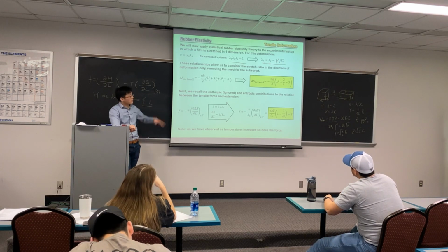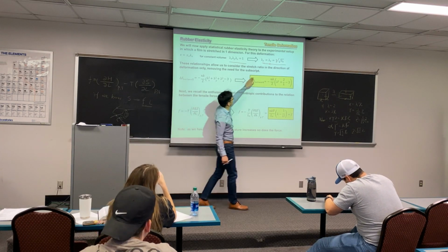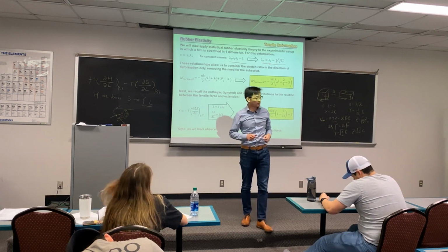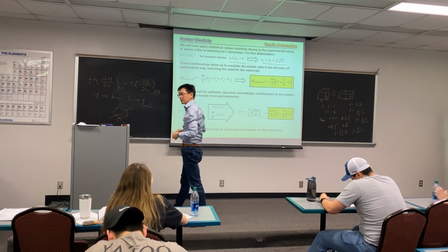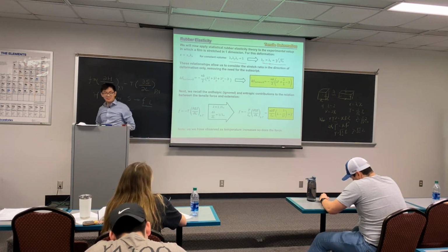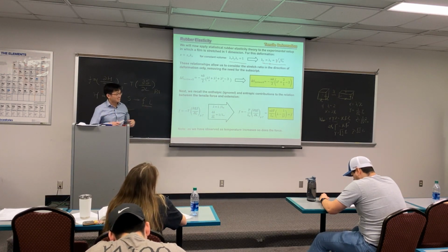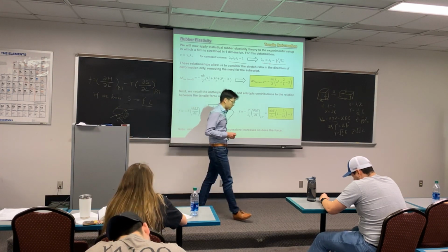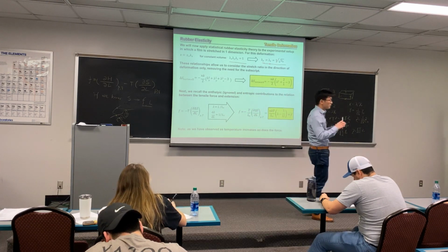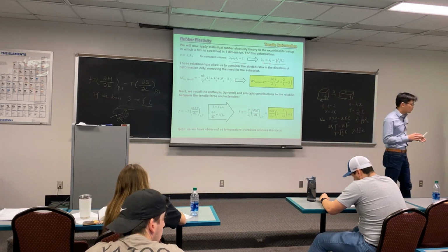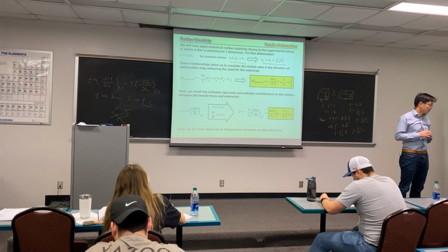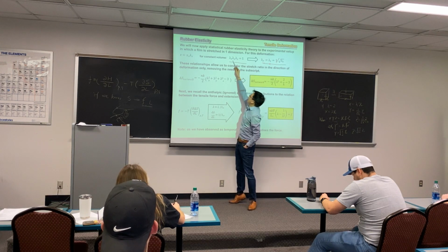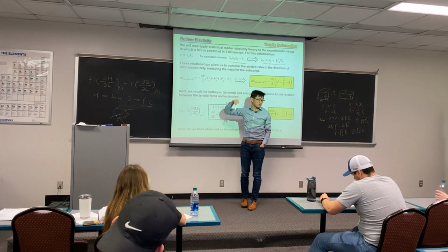Any problem for this one? I want to make sure this is captured. If not, then the rest will be a very smooth downhill skiing trip. Is this because it's isotropic? No, it's because there's incompressibility in the system. So when we deform, the volume of your polymer or elastomer is constant. So lambda x multiplied by lambda y multiplied by lambda z will equal 1.